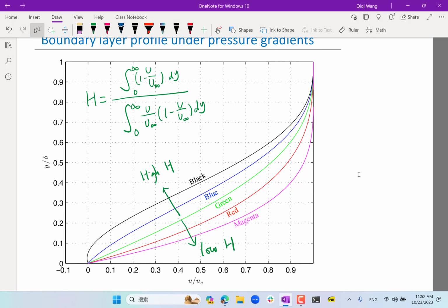Agreed? So both at y equal to 0 and y equal to 0.1, the flow sandwiched in between these layers are dragged forward by viscous forces. This is actually always the case as long as you have a curvature of the fluid like that, right? As long as you have a curvature that's opposite of what we see in the pressure-driven channel flow case. In the pressure-driven channel flow case, the profile is like that, right? The curvature is like this.